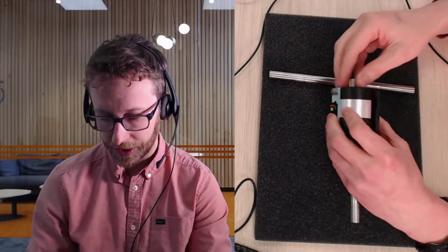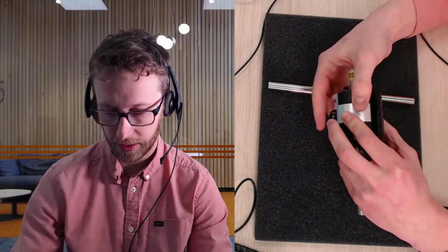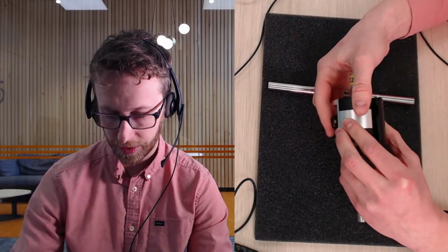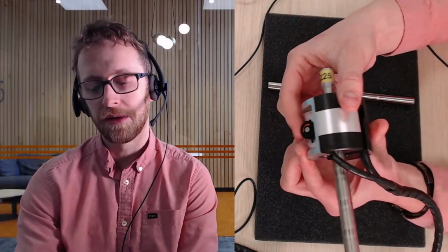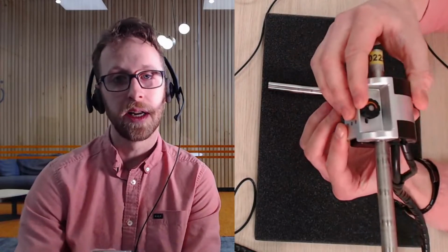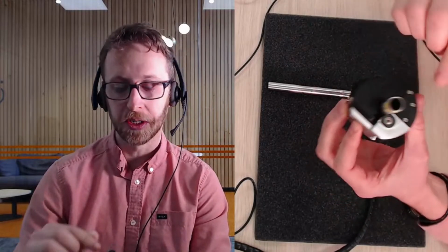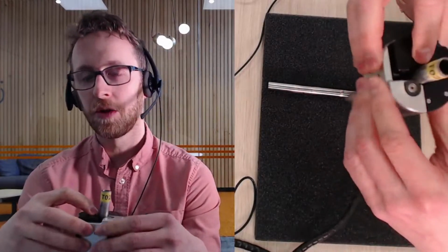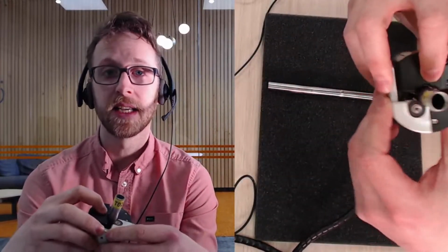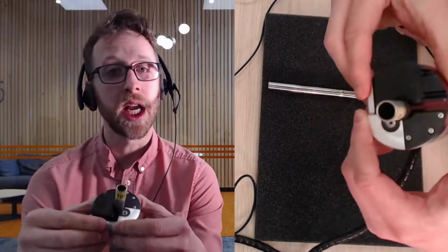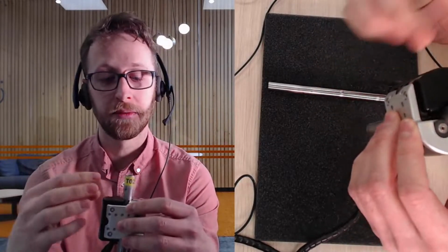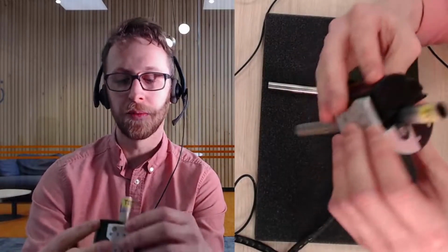So if I just insert the sample inside the probe and I just close it. Now I close it until I feel some resistance here. I don't need to close it that much. As I said, there's a spring-loaded shoe, so once it reaches that sensor array, you will feel some kind of resistance. There's no worry about tightening it too much. The probe body itself is designed with 2 grooves on each side that protect the sensor arrays. So if you close it a little bit too much, the tube is going to reach that side of the probe and you won't be able to push it further.